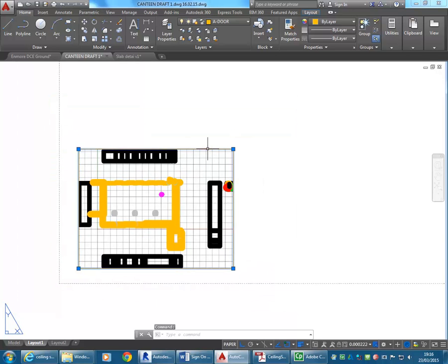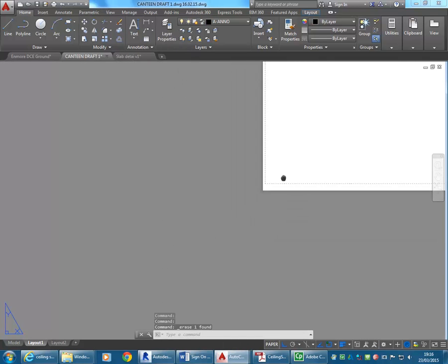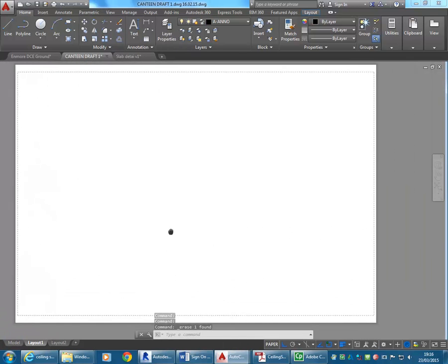And this is a viewport. If you haven't done much with layouts before, that's just a view of everything we've drawn. Because it's so small, I'm not going to try to fix it. I'm going to delete it. With it selected on the border, click on the erase button, and I've cleared the page, and I can make my own viewport.